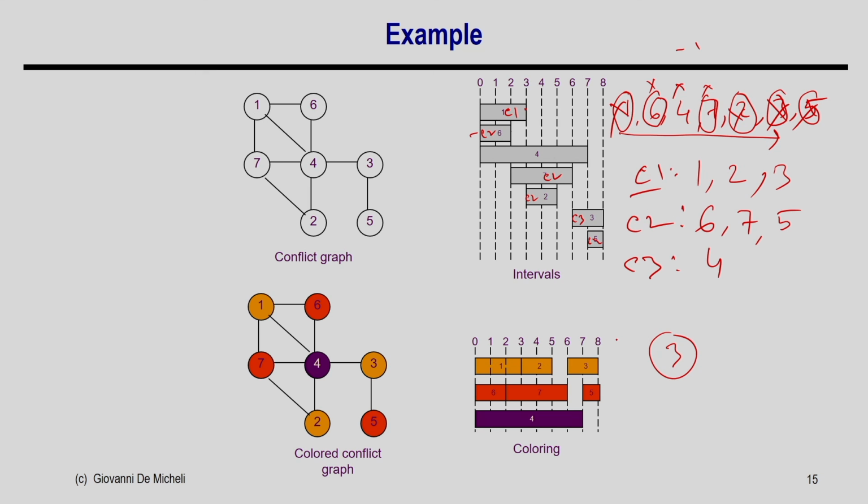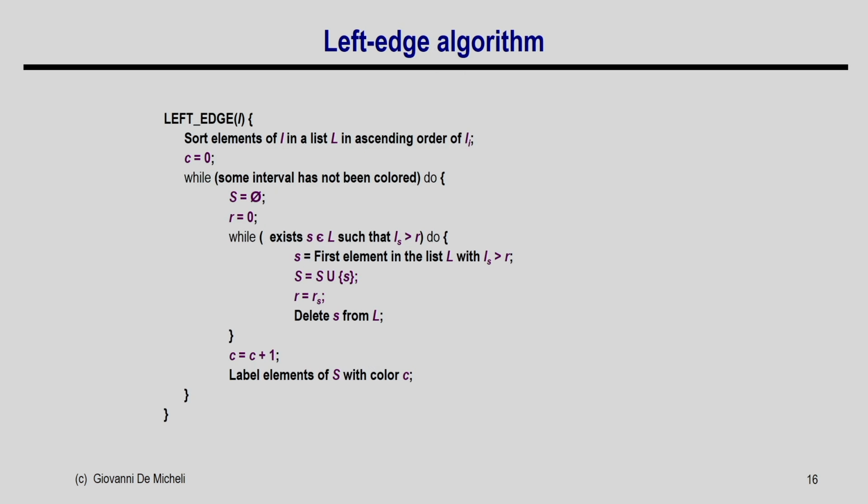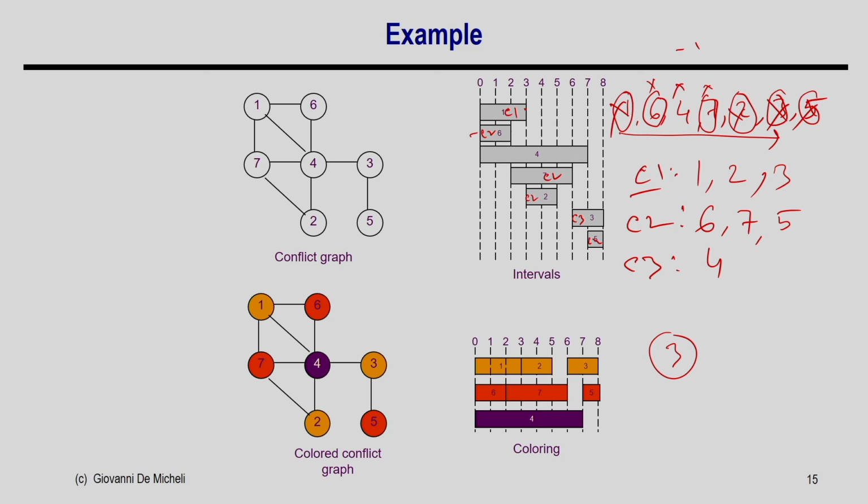Okay. And also the mapping of each of the nodes or the operations to the FU is determined by the left edge algorithm. Okay. So, I will just formally explain the algorithm. It takes the intervals I, which are given by the left edge and right edge, and then I am going to sort the intervals based on the left edge, not by the right edge, it is by the left edge. So, you can see here it is already sorted by the left edge.